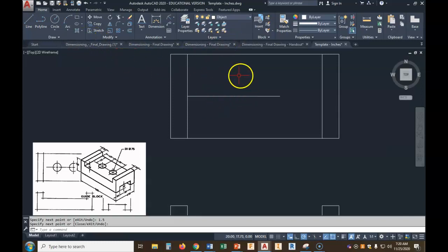You know, at this point, I do go ahead and I want to put these on the center line layer because I want to know I've got that done. That way I don't forget. All right, so let's go to circle. Let's go to diameter just to make it easy. Of course, that end point is my midpoint. It's 0.75, and I started in diameter, so there it is. I need another one just like it over here. I could do the very same thing, or I can go copy some end point, because it was the end point of the line, to the end point of the line, and there they are. They're in the right place, okay?